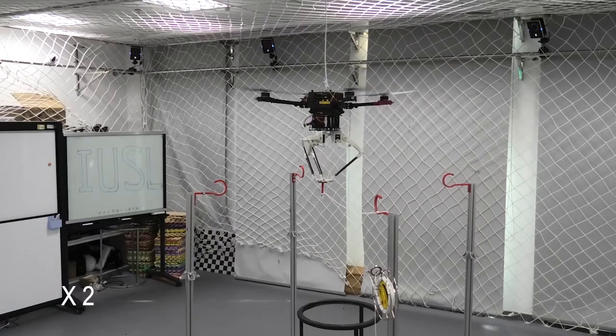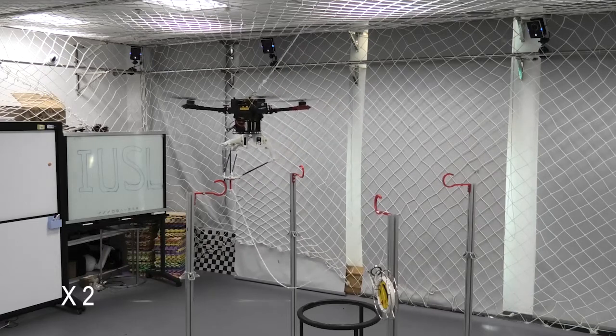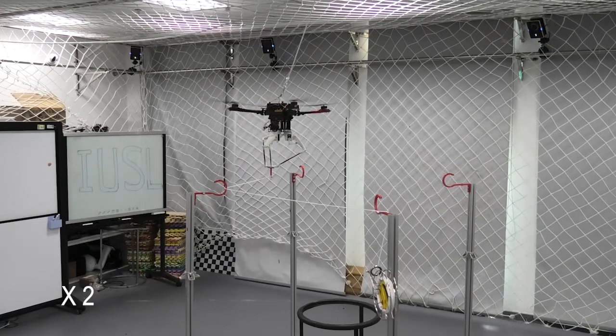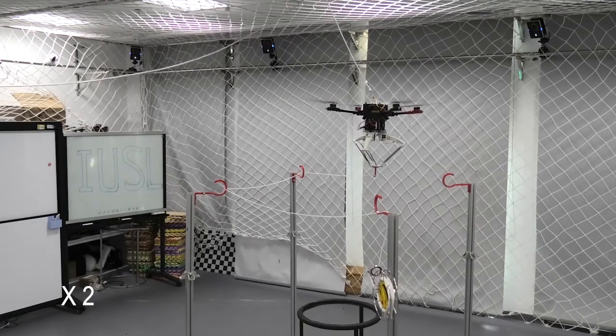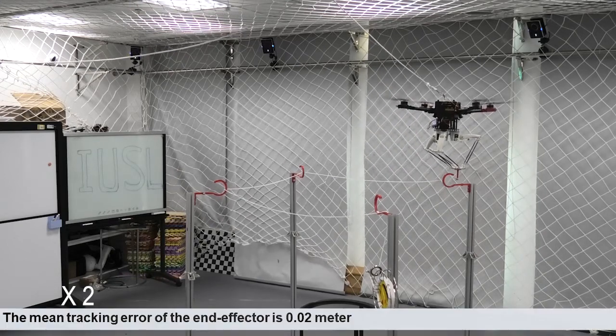In particular, the mean tracking error of the end-effector is 0.02 meter, which is greater compared to the third example where the mean tracking error is 0.01 meter. This is reasonable due to the drag force of the rope. Since force control is not specifically considered in our algorithms, the present performance verifies the ability of the proposed algorithm to counter external forces applied to the end-effector.